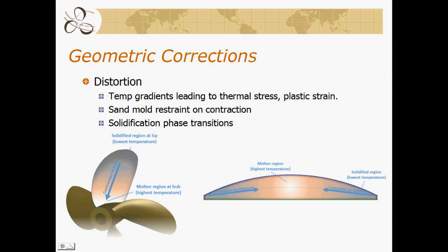How long do they leave the casting inside the mold? Typically, the longer you leave it in the mold, the less problems you have with drooping of blades. But it would be something that we could compensate using a rake correction. That's a good question, Wayne. Thanks.